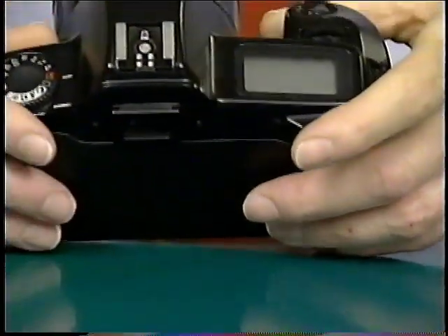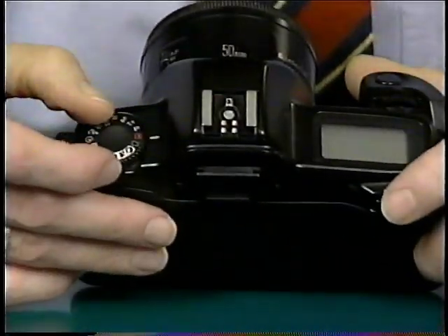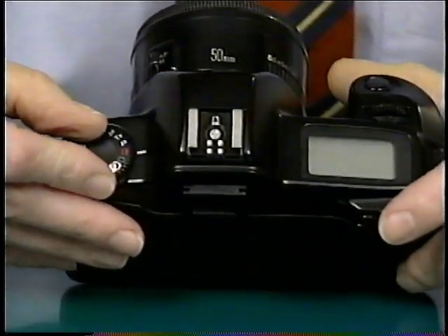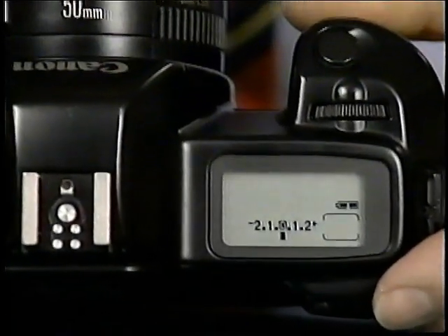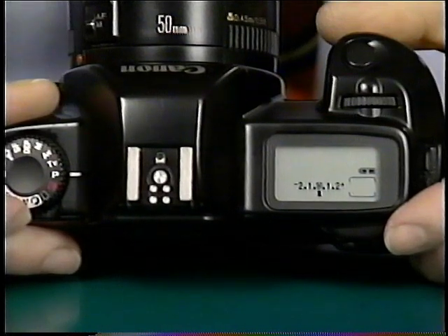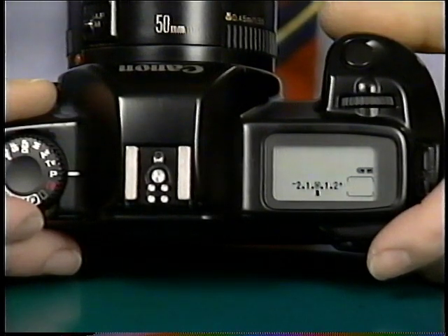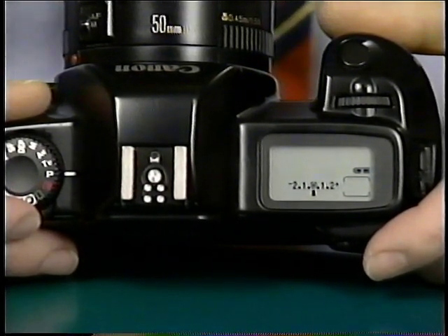And finally, with a single lens reflex camera, this particular one, which is a Canon Rebel, does nothing at all when the battery is put in, but when the main switch is turned off of lock onto the program mode, you will see a display appear in the LCD. In other words, when it's in the off position, there's nothing. When it's on and you see a display, then you know that the processor is awake, and at least the brains or the microprocessor in the camera are functional.